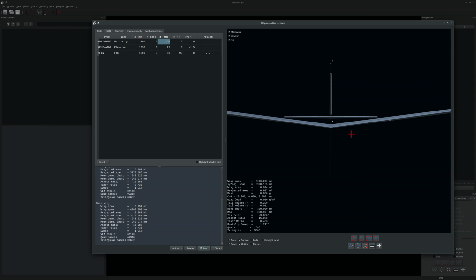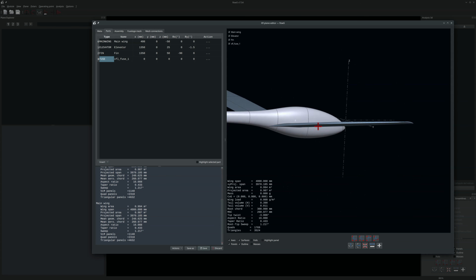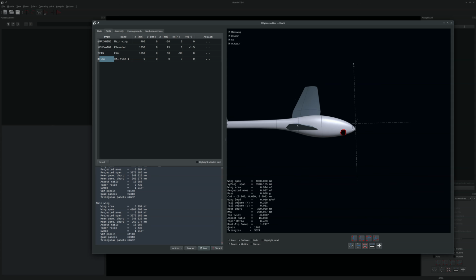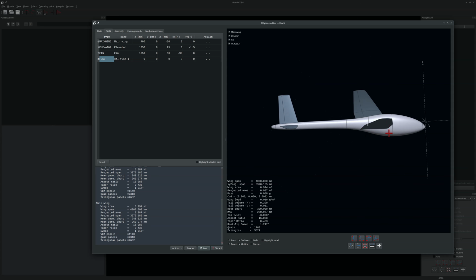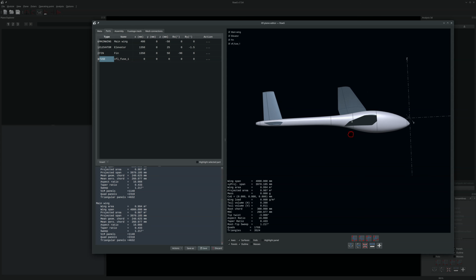Well, this three-part configuration is ready to use, but to be complete, I'll add a fuselage, which I will bring in from the XFL type, the ones we have in XFL5, NURBS and quads. I'll use the NURBS type here. It will show up in a second. And let's see, well, it's been built seemingly in the right position. It's almost tangent here.